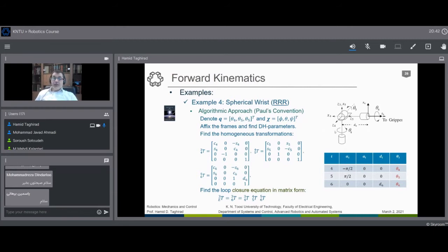One actuator, as we call it, in the Z-axis. As you see in this direction, we have the Z-axis here, and then we have a perpendicular axis to it. We have another rotation we call theta 4. We start with theta 4 because usually the wrist is on top of the arm. So we have 3 angles for the arm, as we had in the previous slide, and 3 angles for just the wrist, 4, 5, and 6.